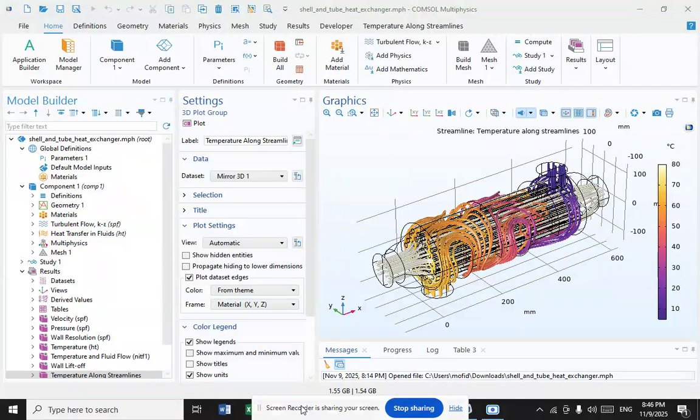The pillow plate can be constructed using either a thin sheet of metal welded to the thicker surface of a tank or vessel, or two thin sheets welded together. The surface of the plate is welded with a regular pattern of dots or a serpentine pattern of weld lines. After welding, the enclosed space is pressurized with sufficient force to cause the thin metal to bulge out around the welds, providing a space for heat exchanger liquids to flow and creating a characteristic appearance of a swelled pillow formed out of metal.